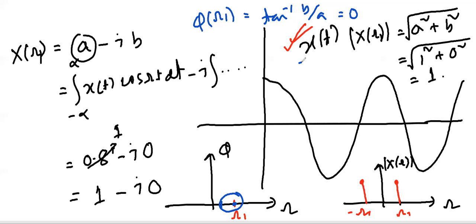This unknown signal is a pattern. What is the phase? From this phase, we can understand the phase of this signal. When the phase shows 0, it shows that this is a purely causal signal without any delay or any progress. And from the magnitude response, we can understand what frequency component you have inside the unknown signal. And what is the frequency component? This is omega 1.